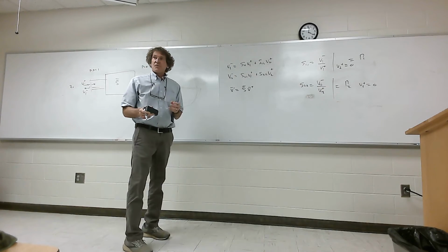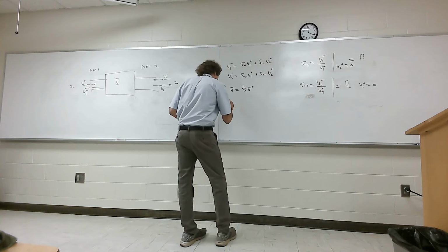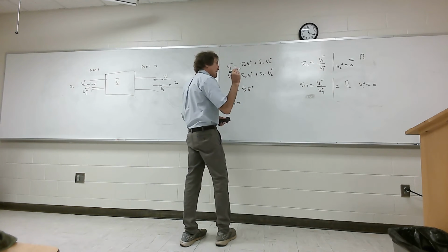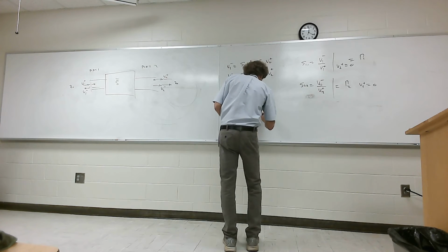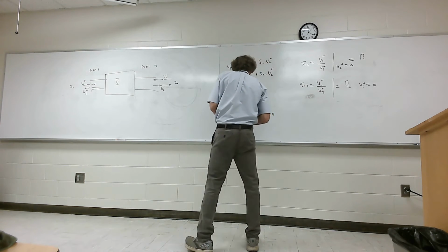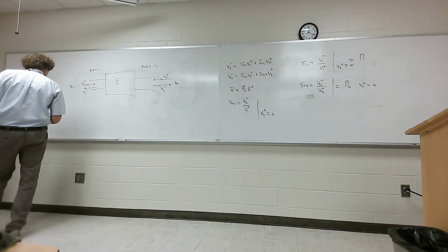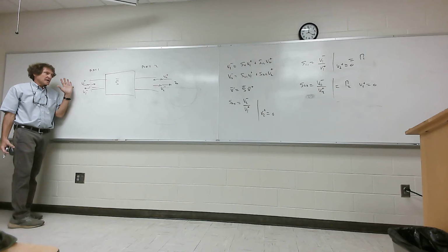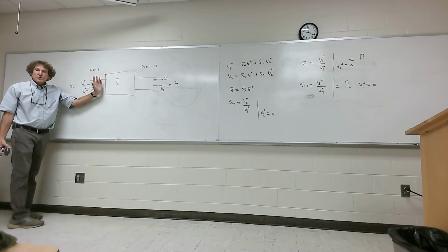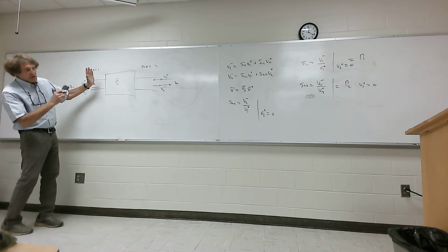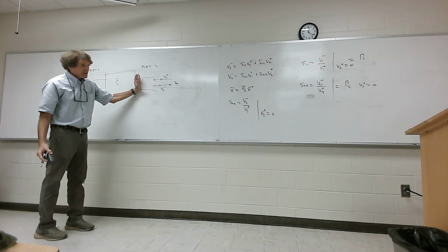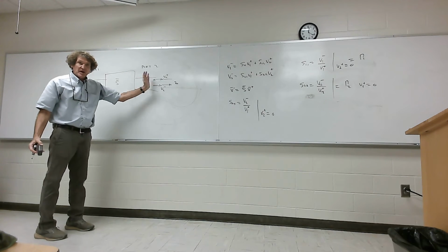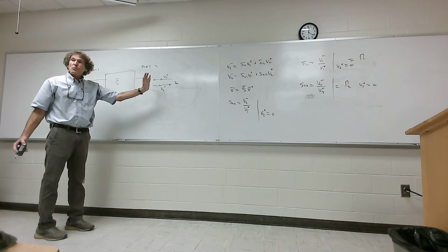The next one is called the forward voltage gain. When you look at S21, S21 is equal to V2 minus over V1 plus, assuming that V2 plus is 0. Take a look at this for a second and appreciate it. Assume a voltage is coming in here with a certain value. When you multiply that by S21, that's the value of the voltage coming out here, V2 minus. Do y'all follow me? V2 minus is going that way. That's the forward voltage gain.